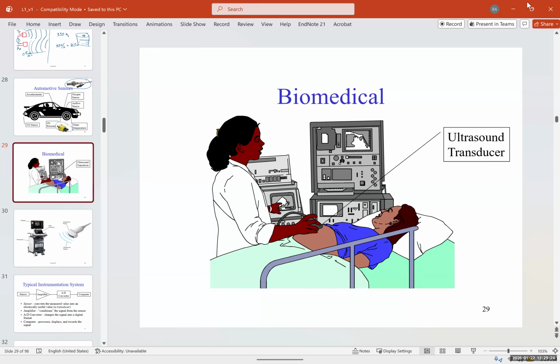Another sensor is the PPG, or photoplethysmogram sensor, as we call it. That is the sensor used in detecting blood oxygen levels, and it also measures heart rate. That's the sensor that you see under the smartwatches and wearables. It has a light, a light sensor. Usually it's an infrared or a green light that you see on your smartwatches. It has a transmitter and receiver. It sends a light signal, and you can detect your heart rate using the PPG. If it uses two different lights, you can measure the oxygen level as well.